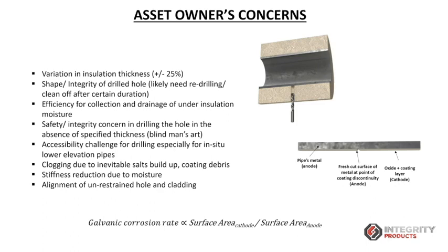And if I receive that 48 millimeter insulation and it's installed in place, and I have to drill in the jacketing thinking that it's 60 millimeter, then there is a high chance during the drilling with the power drills, as API says, that I can hit the pipe. I would say it's a blind man's art. Someone can easily hit the pipe. And even if they are smart enough to judge that it's touching the pipe and stop the drilling, the worst case scenario is that they make a through hole and puncture the pipe.